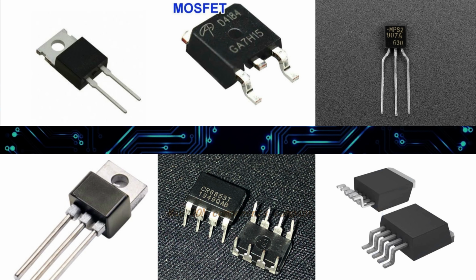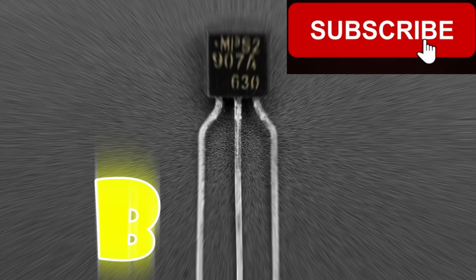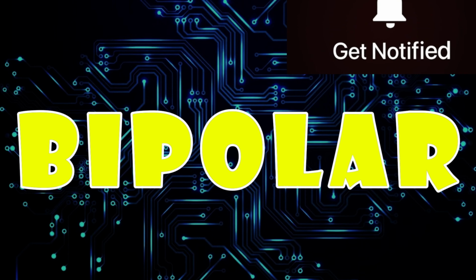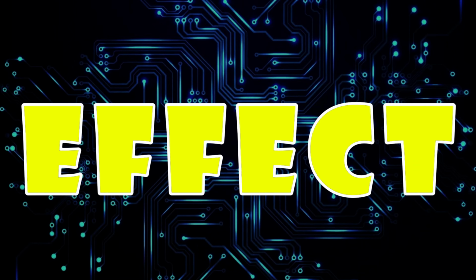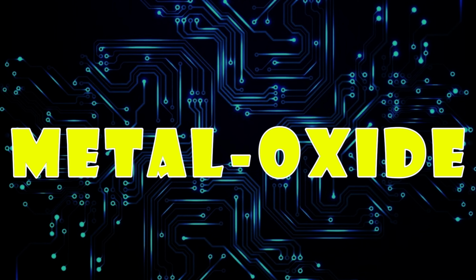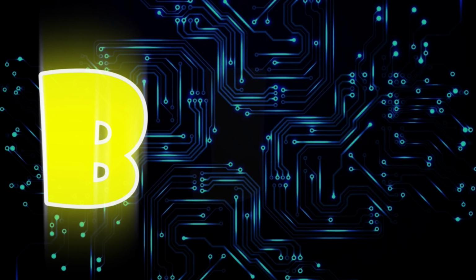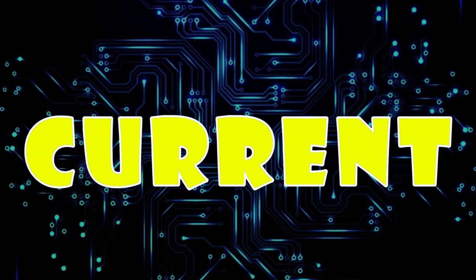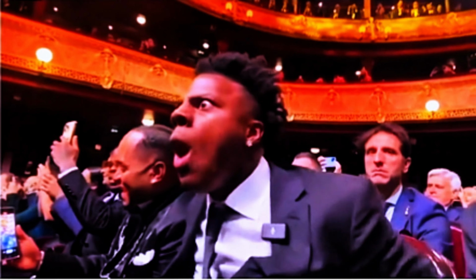There are many transistor variations, but most fall into two major families. For the first, we have BJT, short for Bipolar Junction Transistors. And for the second, we have FET, short for Field Effect Transistors. Under FETs, we also have a very popular version called the MOSFET, short for Metal Oxide Semiconductor Field Effect Transistor. But the biggest difference between these two transistor families is that BJT is controlled using current, and FETs, like MOSFETs, are controlled using voltage. Let's understand what that means.